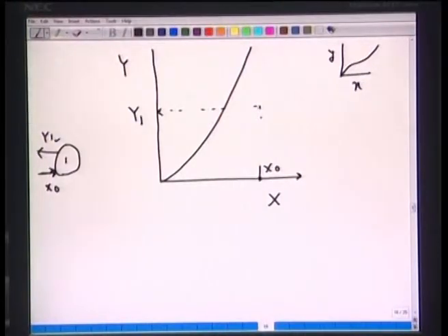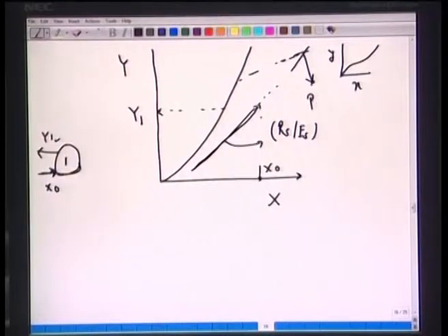Okay. So, we mark here y1 x1, and if you look at the operating curves, now it's linear with a positive slope. So, we have a linear curve with the slope of plus RS over ES. And if some equilibrium curve is like this, it's possible that this operating curve may extend to hit this, and we will call this a pinch. It's a pinch point, right.